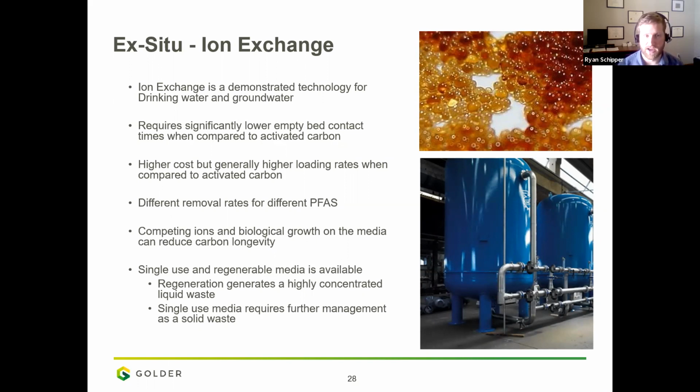The media itself typically has significantly higher cost than the activated carbon, but on the other side of things, it has generally much higher loading rates, so it can load a significant amount more PFAS onto the same volume of ion exchange material. Similar to the GAC, there are different removal rates for different PFAS, but this is much less pronounced for the ion exchange materials, and again, competing ions and biological growth can limit the media longevity.